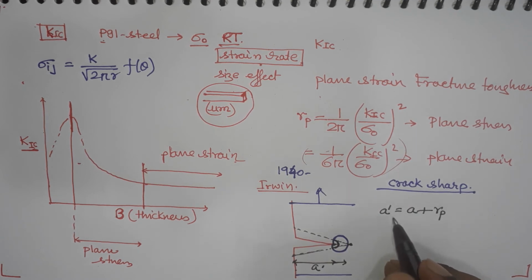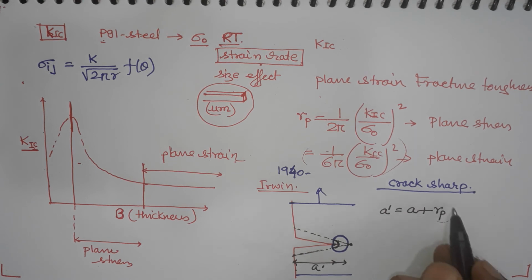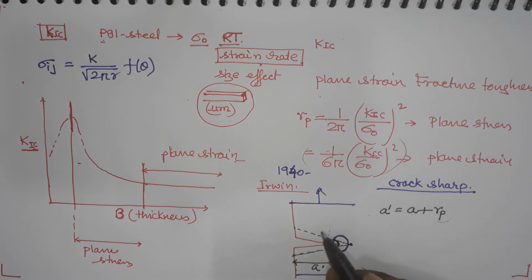It will be causing different problems if the plastic deformation is too high. Okay? If the plastic zone radius is very large, then this virtual crack growth cannot be imagined or assumed, and we will discuss this part also at a later point of time.